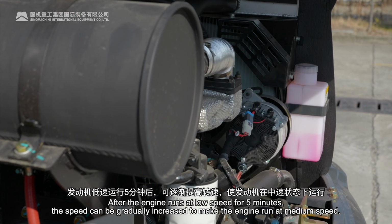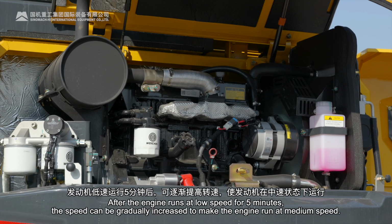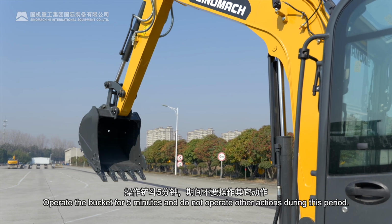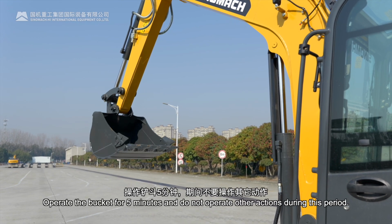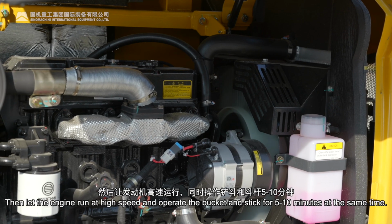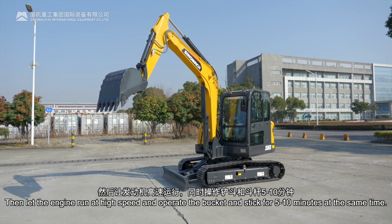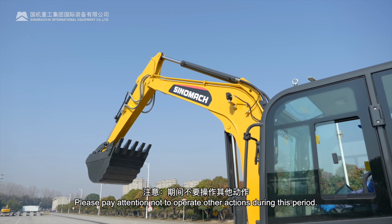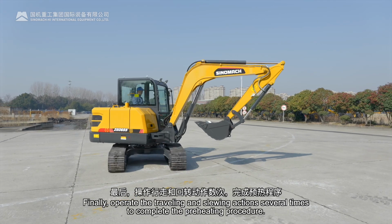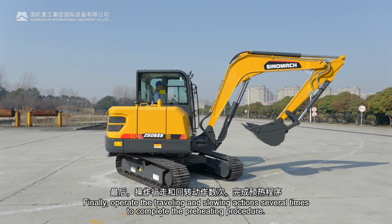After the engine runs at low speed for 5 minutes, the speed can be gradually increased to make the engine run at medium speed. Operate the bucket for 5 minutes and do not operate other actions during this period. Then let the engine run at high speed and operate the bucket and stick for 5 to 10 minutes at the same time. Please pay attention not to operate other actions during this period. Finally, operate the traveling and slewing actions several times to complete the preheating procedure.